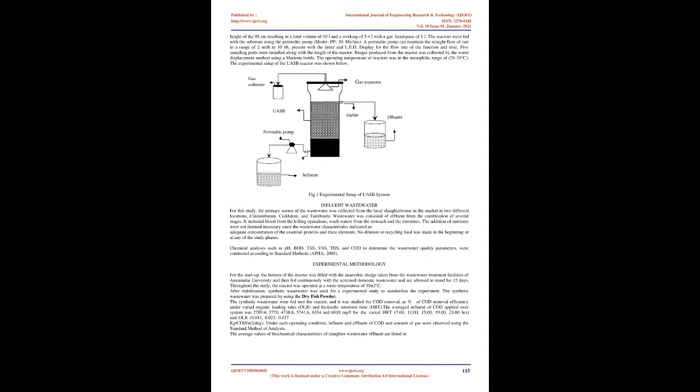In the UASB process, the anaerobic bacteria convert organic material into methane, carbon dioxide, and biomass while purifying the wastewater, Del Neri et al., 2001. UASB systems were known for their high volumetric treatment rates, good CH4 productivity, and low sludge production, making the process economically and technologically attractive. Del Pozo et al., 2000.